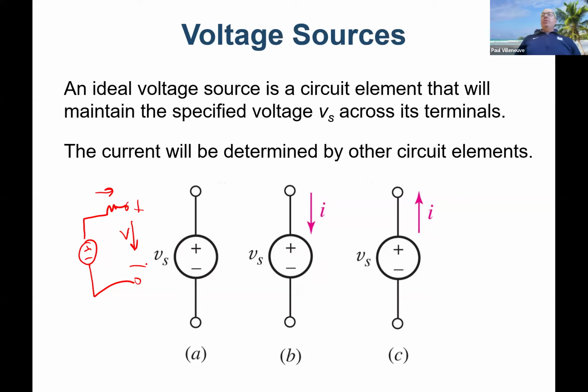So the voltage determines the magnitude as well as the polarity. The current out of that is all dictated based on what the load looks like. And an ideal voltage source means it can supply an infinite amount of energy, but it also can absorb an infinite amount of energy. Remember, all a voltage source is trying to do is keep the voltage fixed. So if it has to crank out electrons or absorb electrons, it should be able to do both, right? That's why we can flip-flop the direction of current, and the ideal voltage source should be able to handle that without any problems.